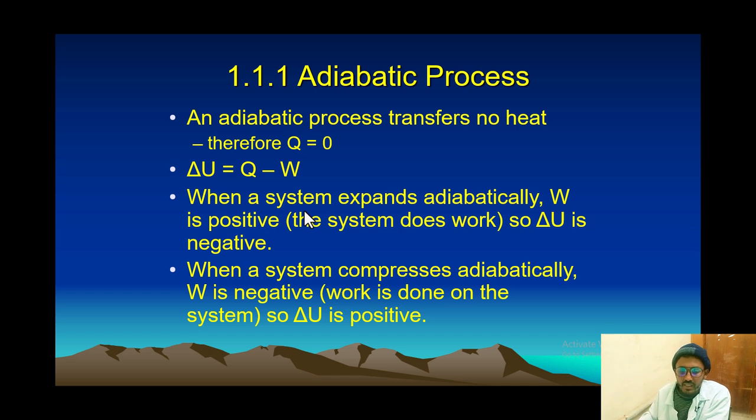So let's see about the adiabatic process. An adiabatic process transfers no heat, therefore Q is 0. So we have this one, right? This one is 0, so we have the change in internal energy is equal to negative W, work done. So what does this mean? When a system expands adiabatically,